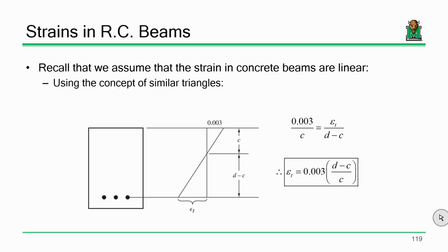A doubly reinforced concrete beam being one where we have rebar here and here, okay? Which we almost always have anyways, because when you build a rebar cage, you've got the rebar on the bottom, the rebar on the top, and the stirrups tying everything together. If you account for that rebar up top, you get benefit in long-term deflection performance, and also you have to account for it when you're looking at columns anyways.